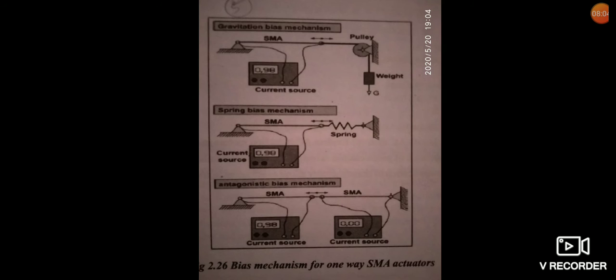Shape memory alloy is used for such things as actuators, which are materials that change shape, stiffness, position, natural frequency, and other mechanical characteristics in response to temperature. Shape memory alloy actuators are made as wire, spring, or ribbon shapes. They are able to produce extreme forces from the viewpoint of the volume to force ratio. On the other hand, shape memory alloy elements can only provide force and displacement in one direction. For example, a wire that contracts when heated does not expand without external force when the alloy cools down. This is the disadvantage of one-way shape memory alloy actuators.